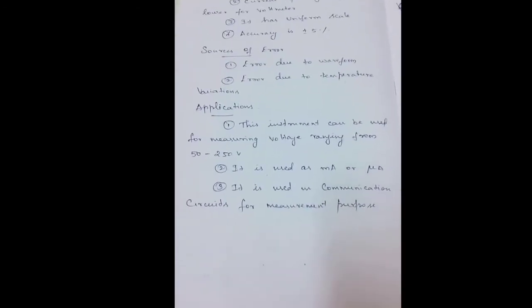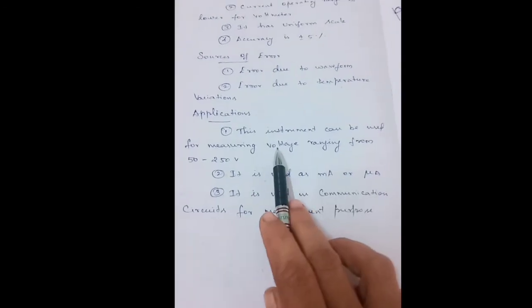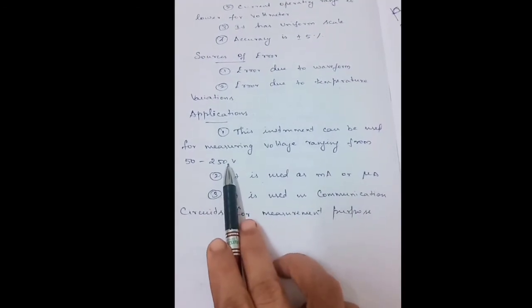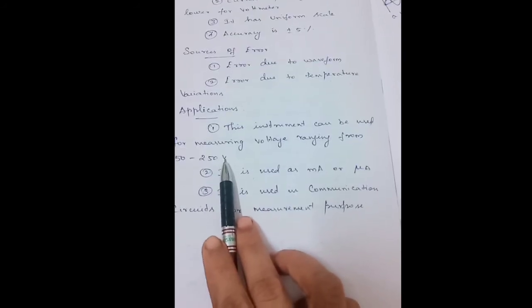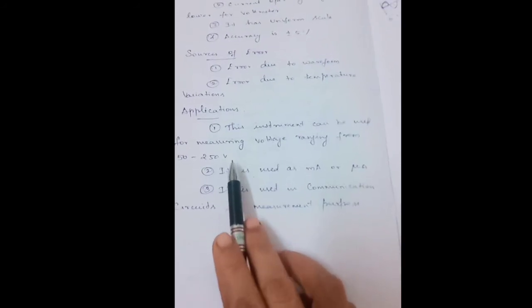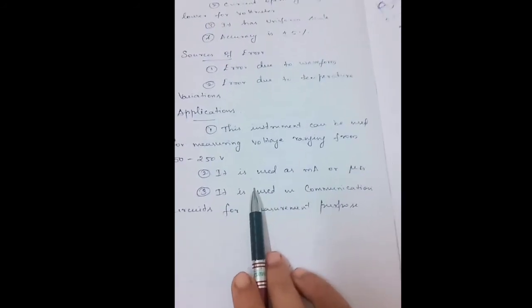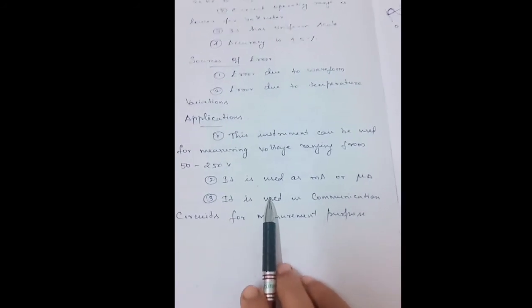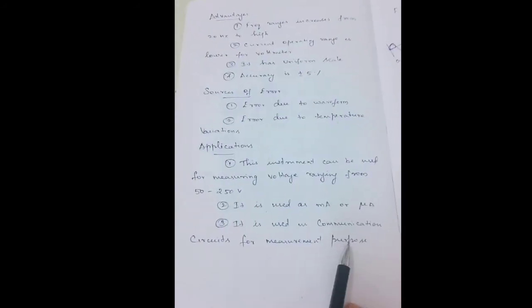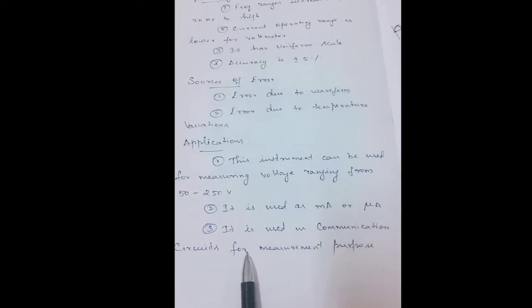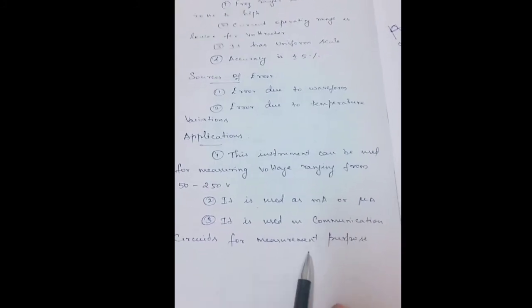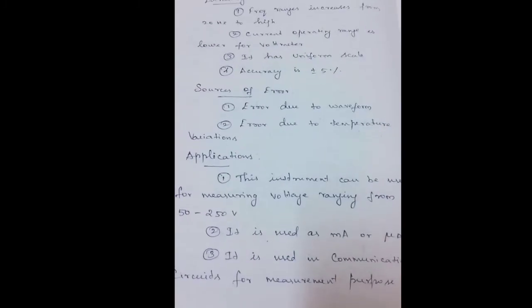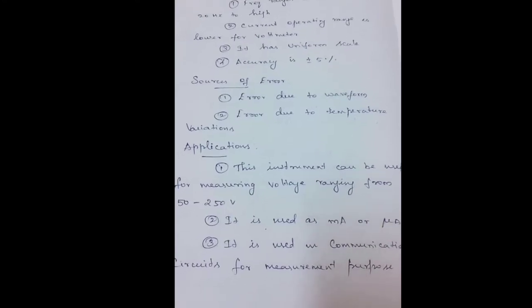Regarding its application, this instrument can be used for measuring voltages ranging from 50 to 250 volts. These instruments are meant for measuring lower values of currents, in the range of microamps or milliamps, and are also used for measurement in communication circuits, that is, audio and radio frequency range circuits. That is the major application of this instrument.